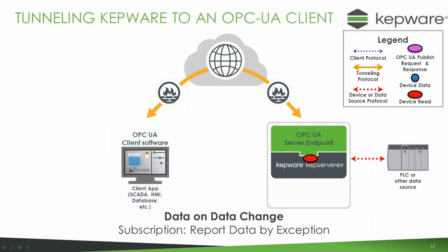You can do something similar using application software on the left, which is itself an OPC UA client. You might consider this to be a half tunnel, or just a normal OPC UA tunnel across a firewall. On the right-hand side, you have the PLC data being polled, and when there's new data, the client application on the left will be notified and it would come and collect it. So there's no OPC UA tunnel client on the left-hand side, it's actually the native OPC UA client itself. The connection through the middle is simply using a single port specified by you, encrypted and secured in both directions.